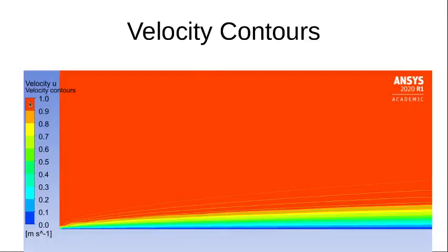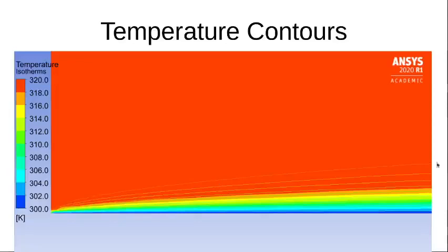You can see that here it has not exceeded 1 by a great amount. It's still staying put. And you can see that with the same magnification of 20, the boundary layers are much thinner. So if this is, let's say, 2 or 2.5 centimeters, you can see that this is well under that. The thickness of the boundary layer is just about 1 centimeter or less. And the thermal boundary layer is also of this kind of thickness. The thermal boundary layer is much thinner.